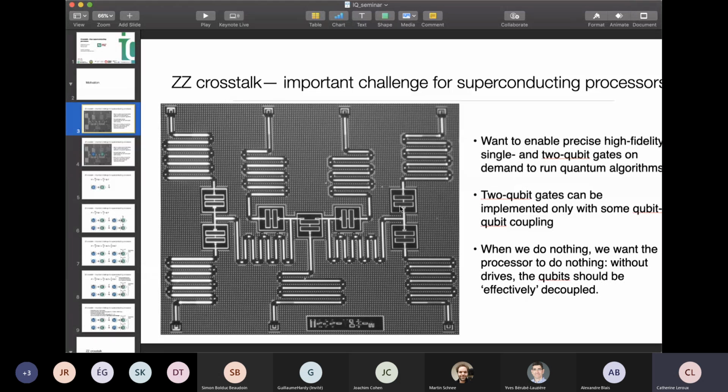gates between two distant qubits using, for instance, an intermediate qubit, like a virtual gate, if you want. So there are possibilities without having direct connectivity. There's also the possibility of using a coupler, or a bus, and connecting multiple qubits through it and doing parametric interactions between pairs of qubits. So there are very different approaches, but having all-to-all connectivity is more difficult to do anyway. So for superconducting circuits, I'd say it's not the most pursued. Okay. Thank you very much.